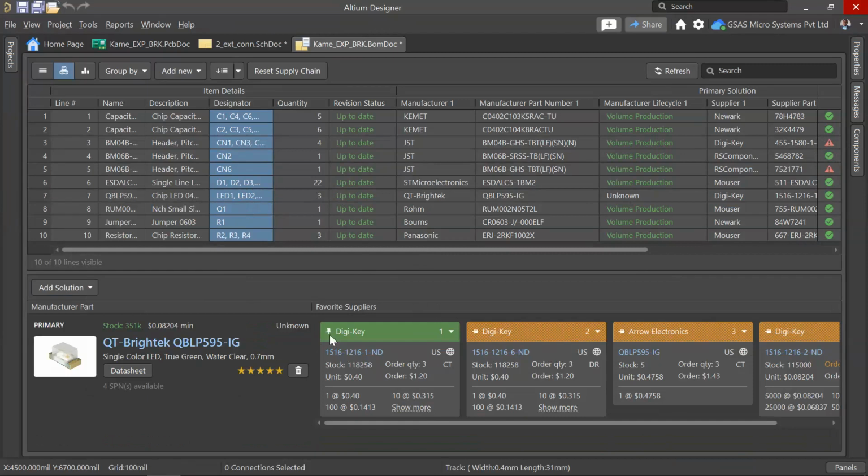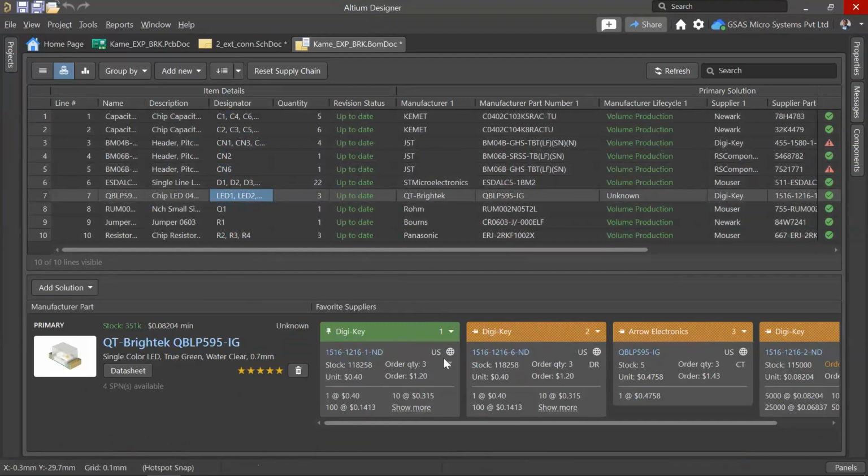Here we can notice it has been pinned, that means this is the component which needs to be used for this LEDs. So if I want to change this component with this one, then you can unpin this and change the priorities. If I pin it, I can't. Like this, this is my pinned component. Like this you can unpin it and change the ranking.